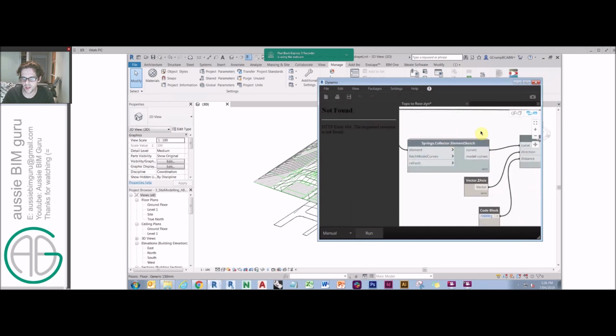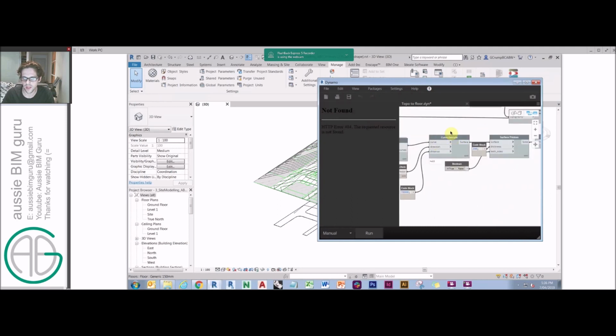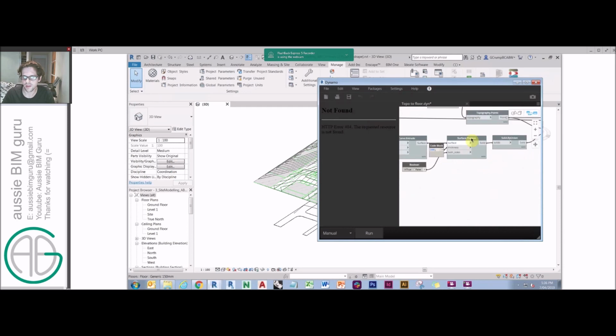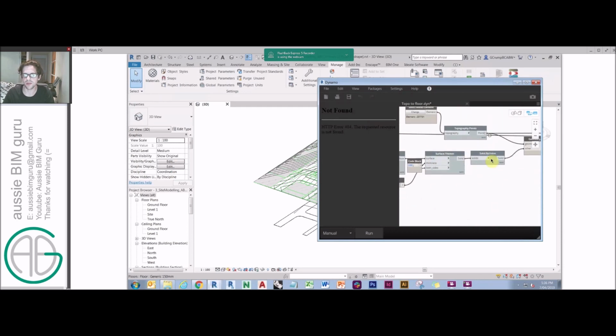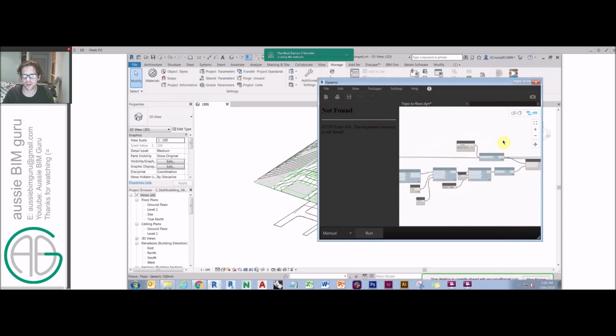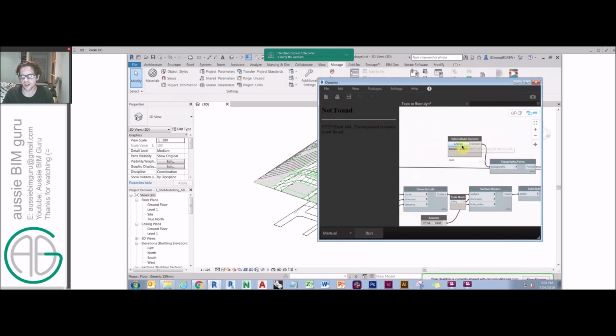It will collect a sketch of that floor and it will then extrude it upwards, and I'm basically thickening the surface of it outwards so that I can find everything that intersects around the boundary of the road. So I'm not looking at the internal points of the road, just the edges and how they coincide with the topo surface above, which I'll select here. I'll pick that road surface.